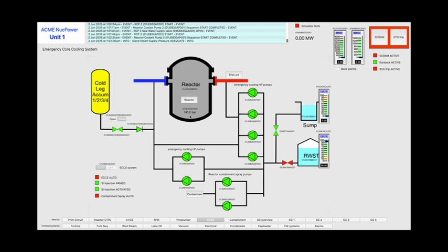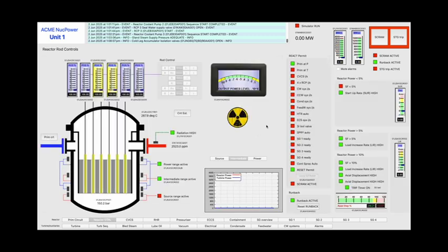At the emergency cooling water system page, we need to wait until the primary circuit pressure is greater than 142 bar, and we can then open the safety injection isolation valve. As we get to operating pressure and temperature, the heaters in the pressurizer will automatically back off to 25%. Now is a good time to check the reactor start permissives to see what other systems are still outstanding to place in service. All reactor SCRAM reset permissives are now met.